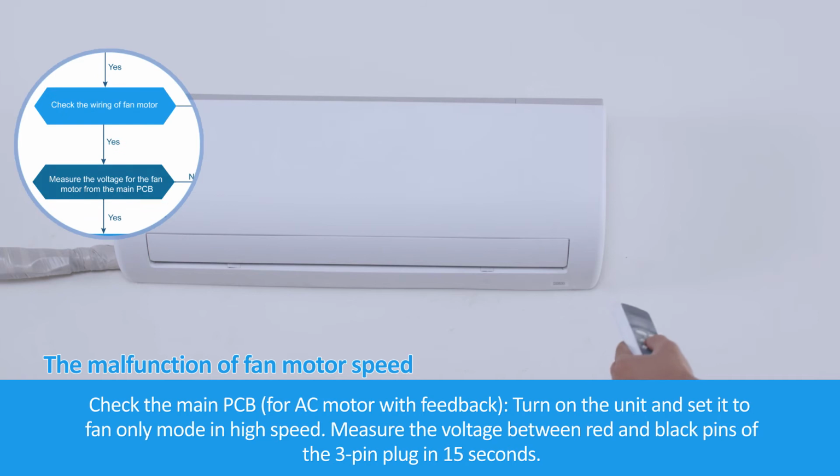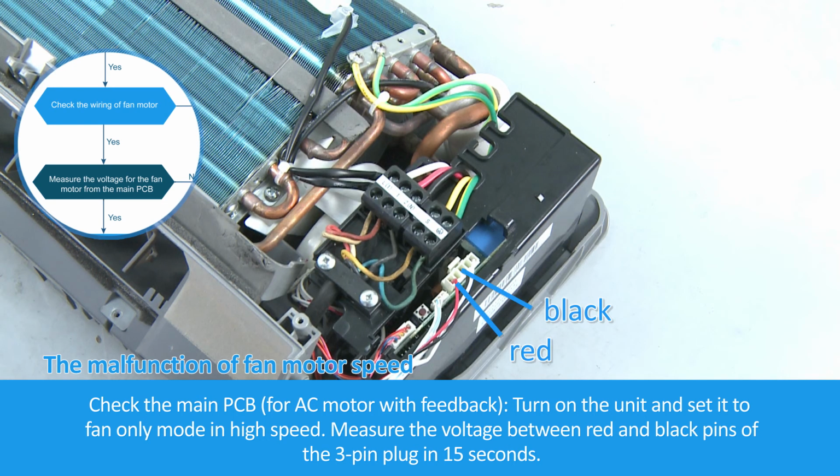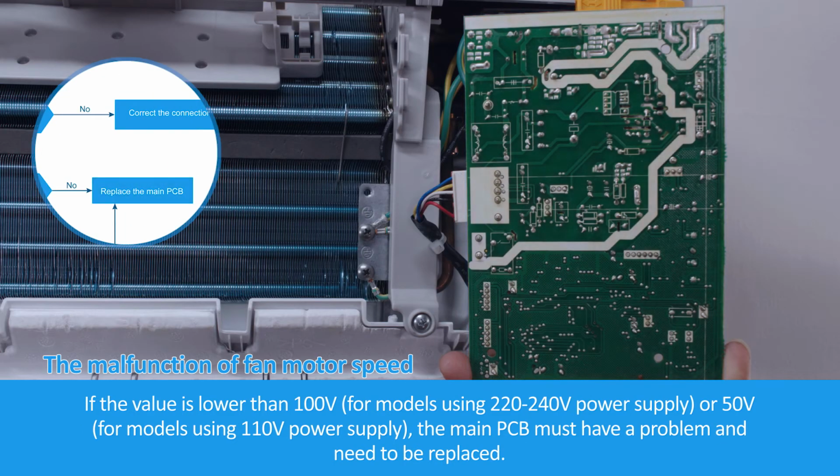Check the main PCB for AC motor with feedback. Turn on the unit and set it to the fan only mode in high speed. Measure the voltage between red and black pins of the 3-pin plug in 15 seconds. If the value is lower than 100 volts for models using 220 to 240 volts power supply, or 50 volts for models using 110 volts power supply, the main PCB must have a problem and needs to be replaced.